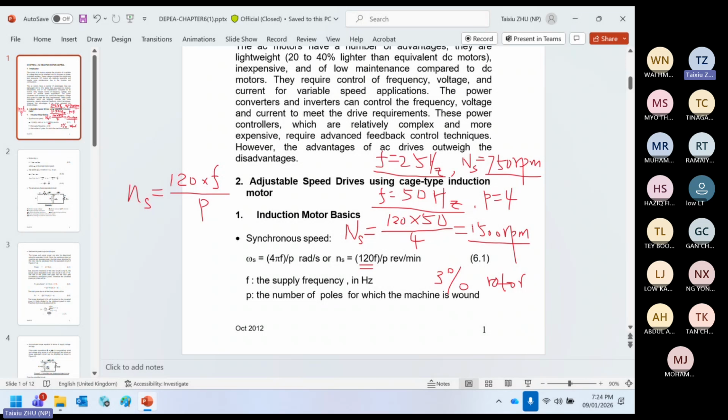Tesla Model S and the Model Y actually use induction motors. The motor can run at 18,000 RPM, but now can run even faster. You can imagine the motor runs at 15,000 RPM. That means your applied power frequency should be 500 hertz. It's quite fast, right? That means quite a high frequency.